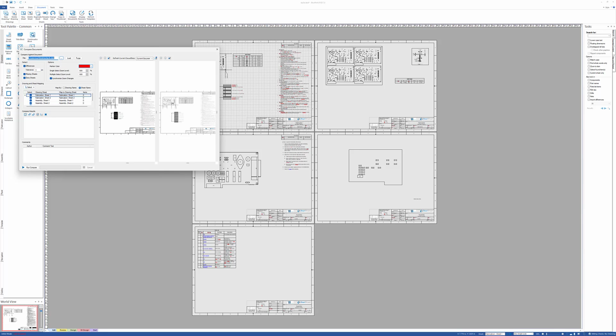Once it is loaded up, you can see the two document sets side by side. You can zoom in and out up here and zoom to the extents if you need to. But let's go ahead and run the comparison. While it's running, I will point out a couple of the other options up here. So first of all, there is tolerance info if you want to have it ignore small differences between the two document sets. You can set this number here.